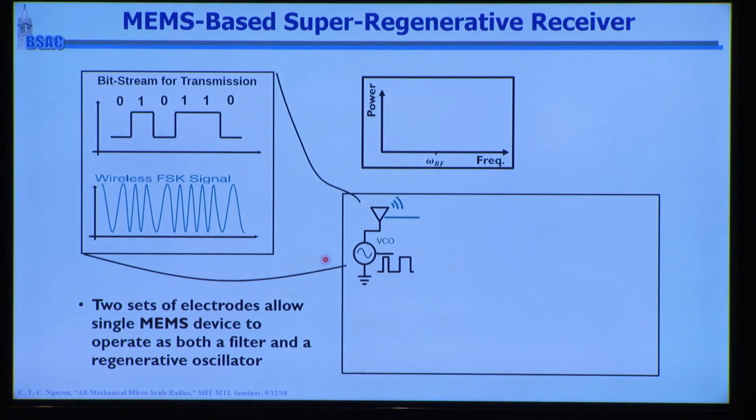Okay, so what I'm showing here is a situation where this is actually a demonstration of wireless reception. This is your transmitter here, and we're doing exactly what we need. We're creating a bit stream that we want to transmit, and we're modulating this onto a carrier, so we're basically making an FSK signal here. Putting that on an antenna with an amplifier, then transmitting that to another antenna on the other side. So these are the zeros and ones. Of course, this is an instantaneous thing. It's really going to look like a spread of frequencies across this.